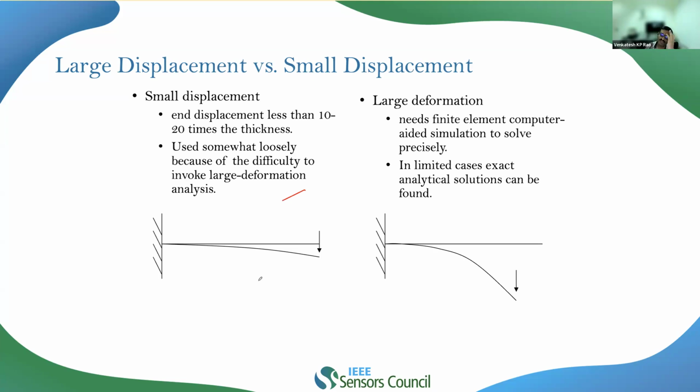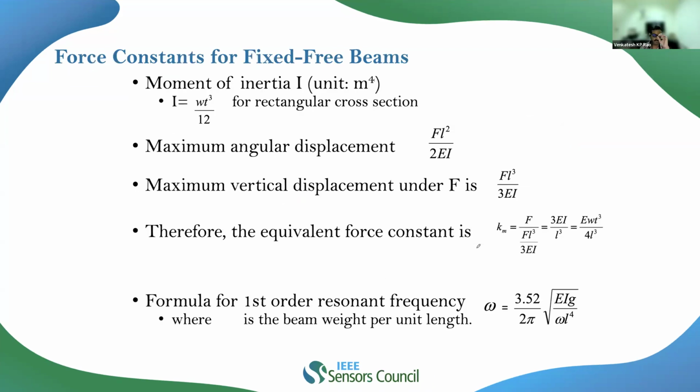On the other hand, if the amplitude of deformations is very, very large, then the nonlinearities will kick in. If the nonlinearities kick in into the system, then you need to go forward for the FEA-based approach. It's not just that I need to go for the FEA-based approach. You can even well solve it analytically as well, but it is a bit time consuming, nothing much. But you need to have some more training with it. First do the analytical things, right? That can still be done. But I would recommend you go with the FEA-based approach if at all it's a large amplitude deformation under consideration.